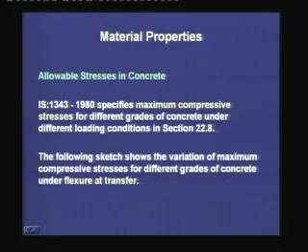There is also another condition, which is the limit state, where the factored loads are used to calculate the demand within the concrete member. Now, out of these different load stages, the load stage at transfer and the load stage under service conditions are checked by the conventional elastic analysis. And in using this elastic analysis, some allowable stresses are specified by the code. It is similar to the earlier working stress design of reinforced concrete.